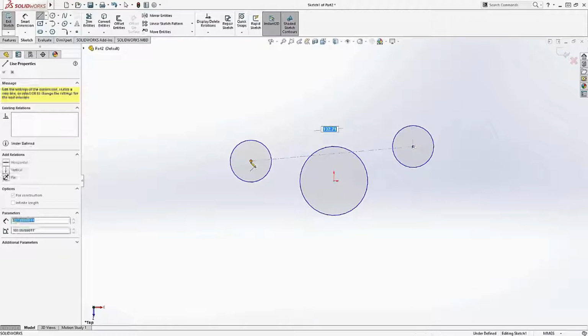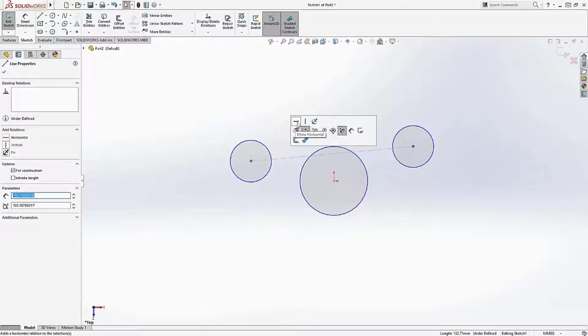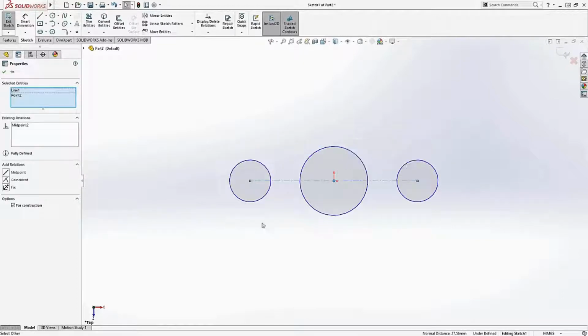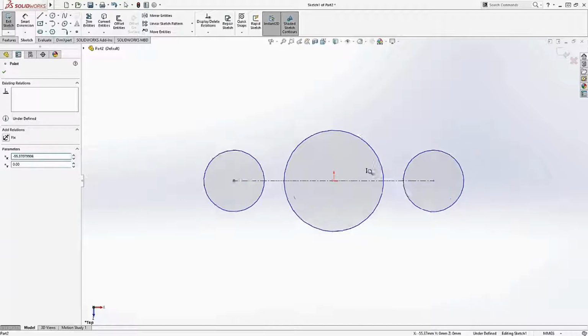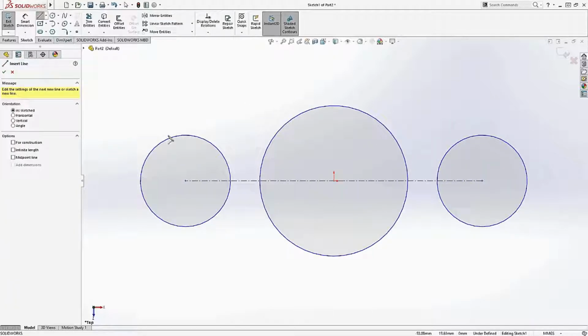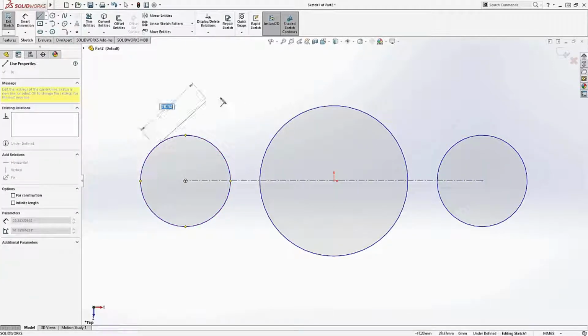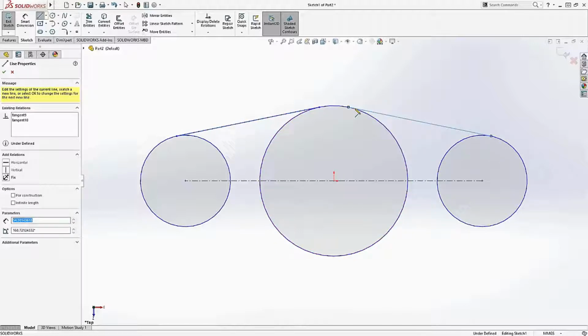Additionally, creating geometry connecting these two together, you'll notice I can lock in things like it being horizontal and if it's locked to the center of the part. So now you'll notice that as I do this, the geometry starts to gain a bit of intelligence. Like snaps in your 2D design tool, you'll notice that SOLIDWORKS intelligently snaps to the geometry. Here, as I move this line across this arc, it automatically snaps to the tangency. So I don't have to spend time creating all those relationships. A lot of them are created automatically.